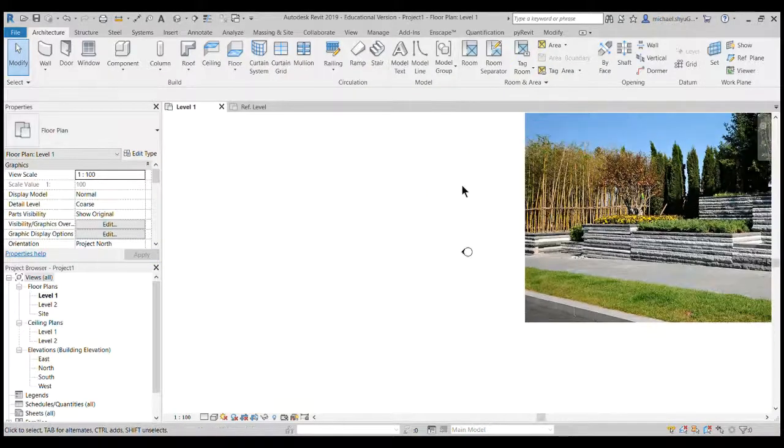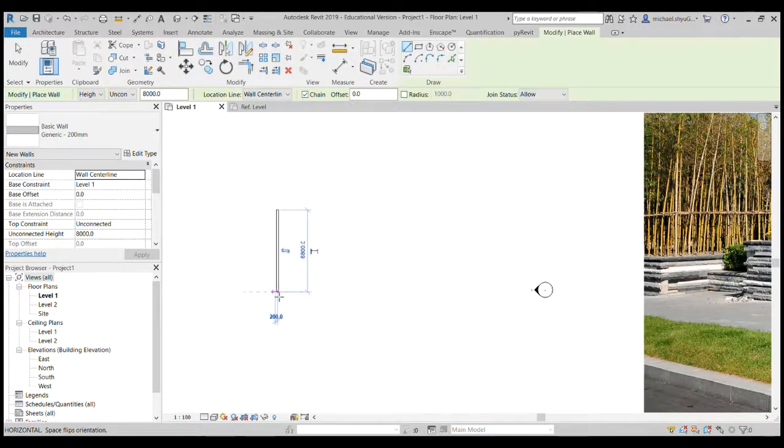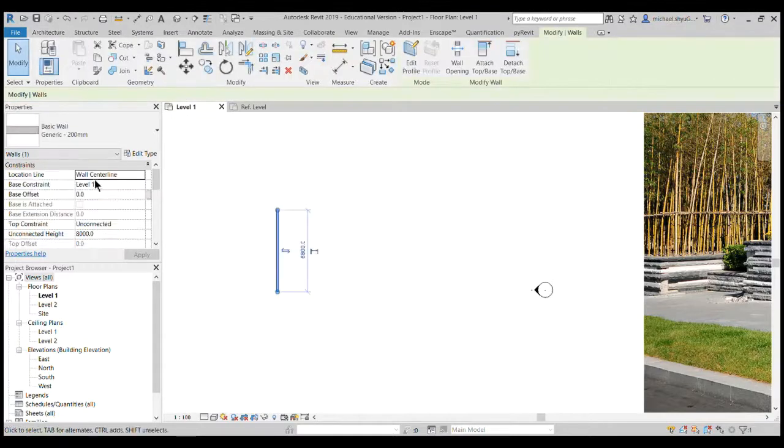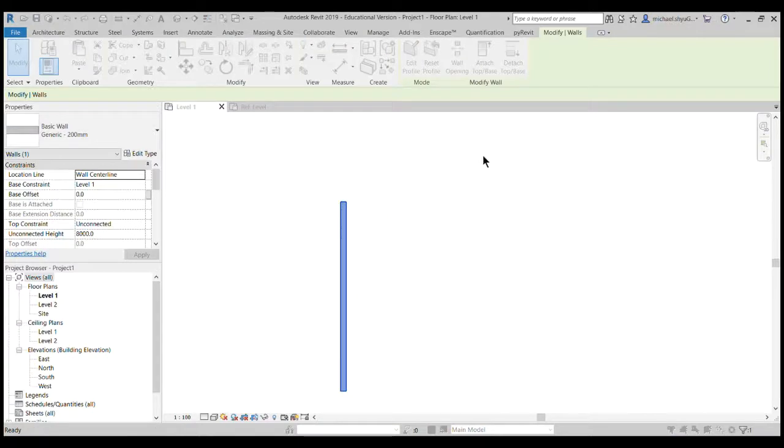All right. In order to create this wall, you first need to edit an existing wall. So let's draw the wall first. Go to Wall, Architectural. And then let's create this striated wall as a wall type. So let's go to Edit Type, duplicate. Let's call it Feature Wall. Click OK. And then now we need to edit the structure itself.